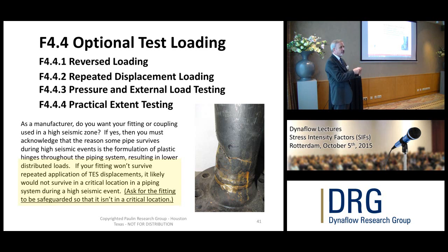The reason that buildings stay alive and the reason that piping stays up in true seismic events is because it's ductile. It bends a bunch at the elbows. The loads are much higher than what we calculate in any pipe stress program we run today. So we have to make sure everything we put in a piping system is ductile. What's not ductile? Junctions, where we put clamps.